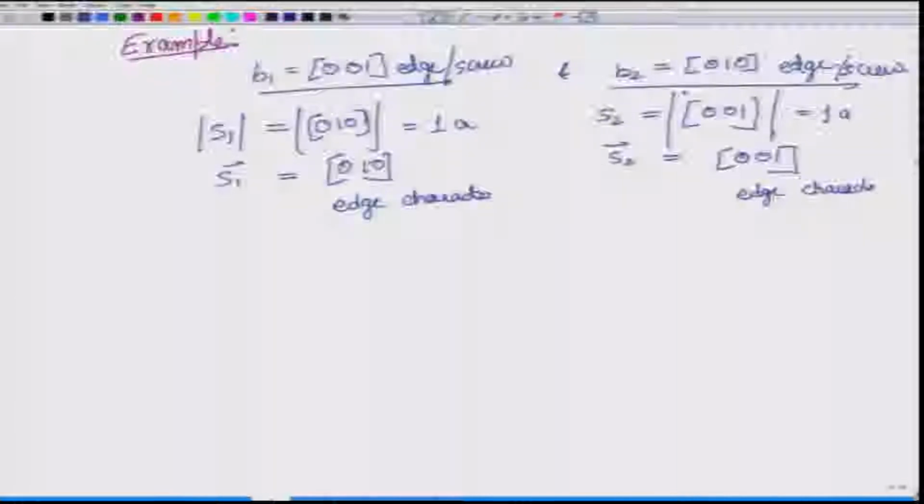And even in the edge dislocation, we never worried about what the line vector is. In fact, for this particular one, if the line vector is along 0 0 1, then this is similar to case 1, where the step is along the line vector and therefore, it is not observable, but we are not worried about that. What we are trying to show is that whether the starting dislocation is edge or screw does not matter, and all that matters is the Burgers vector, because that is what forms the step in magnitude as well as in vector. So, now this is for a simple case.